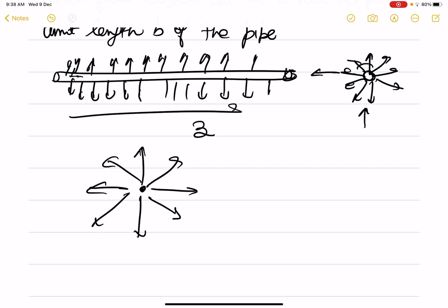So now if I look at a situation where the radial component of velocity goes like 1 over r and v theta is equal to 0. So if this is the situation which is given to us, because this Vr is equal to m over r will come from the continuity equation. If we apply the divergence free condition, we will get Vr is equal to a constant by r.